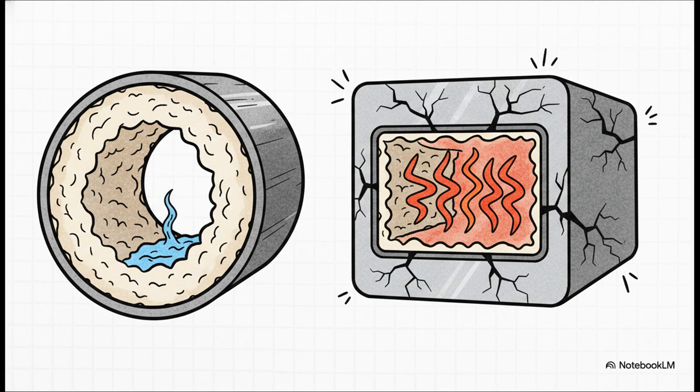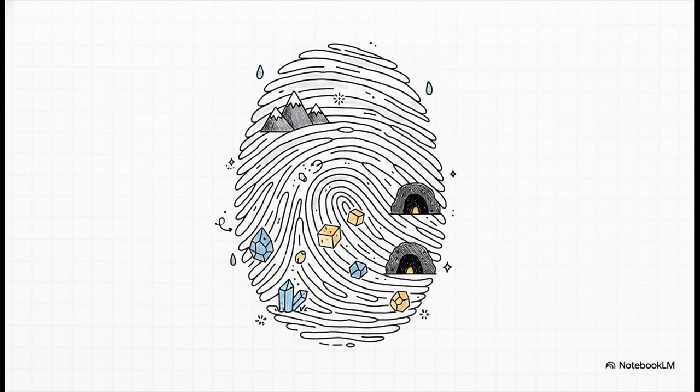And in extreme cases, the chemical reactions within the boiler can cause the metal to become super brittle, a highly dangerous phenomenon known as caustic embrittlement. That can literally lead to catastrophic equipment failure. So, while we obviously spend a lot of time engineering solutions to soften water, using those lime soda processes or complex ion exchange resins we mentioned, it's really helpful to just step back and reframe how we look at it.